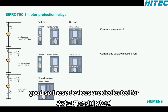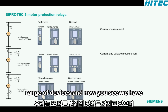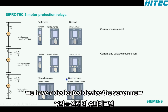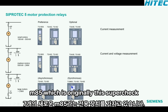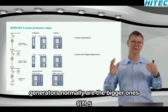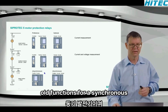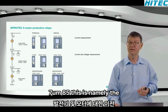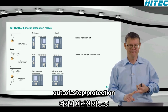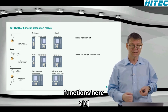Good. So these devices are dedicated for asynchronous motors. We have another range of devices, and now you see we have an overlapping of functions. Originally, we said for the synchronous motor, we have a dedicated device, the 7UM85, which is originally this C-Protect 5 device for generator protection. So generators normally are the bigger ones, synchronous generators, and we have there also functions for a synchronous generator and motor implemented in the 7UM85. This is namely the under excitation protection, maybe the out of step protection, rotor ground fault protection, just to name the most important of these functions here.